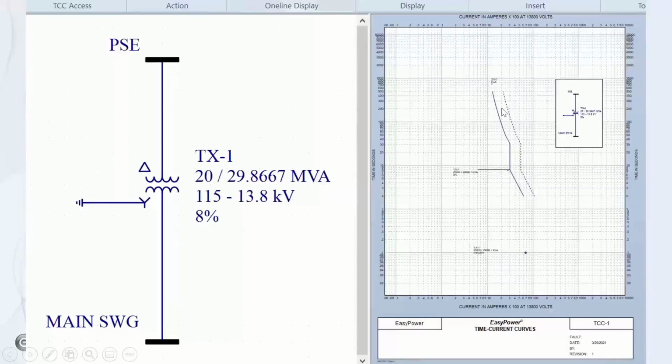Based upon those definitions of terms, the thermal damage is this area of longer exposure to current at this level. We notice the TCC curve has current on the horizontal axis and time on the vertical axis. So if we plot a particular coordinate of time and current, the relationship to these curves gives us an idea of whether or not there's a potential for damage.